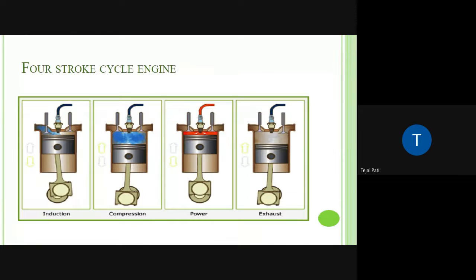Last one, I will finish in 5 minutes. What is in the dry sump? What is happening now in the wet sump? The parts which are away from this spoon, it may happen that at those places lubrication may not take place, or it may not be proper. So in that case, instead of this spoon, small tubings are provided directly at those places where lubrication is needed. So that is known as a dry sump. And mixed sump is a mixture of this. At the far places tubings are provided, at the near places splashing is done. So that is what the mixed sump is.